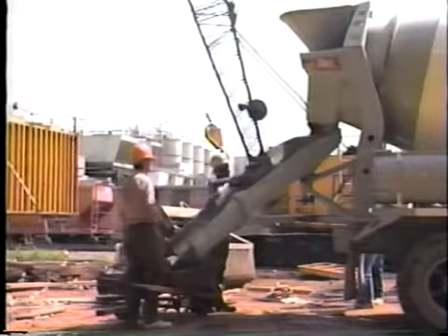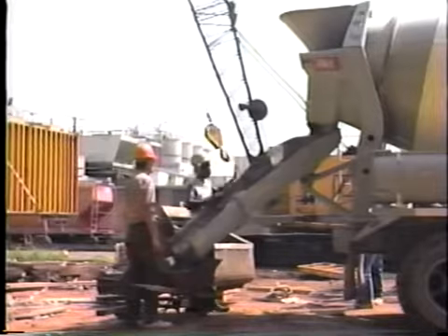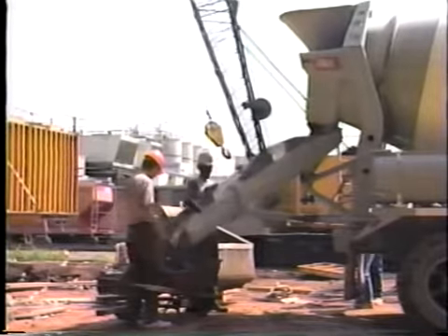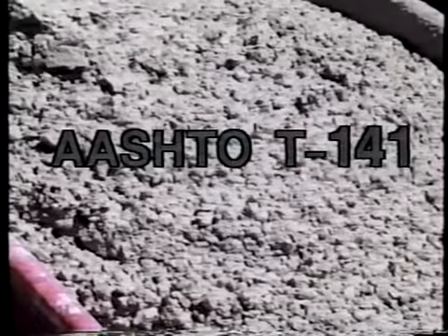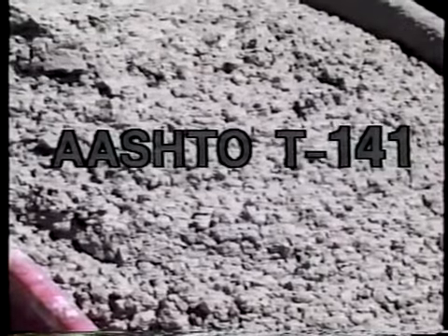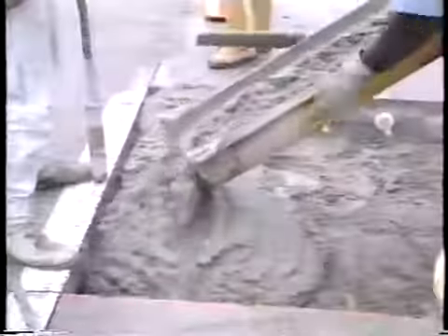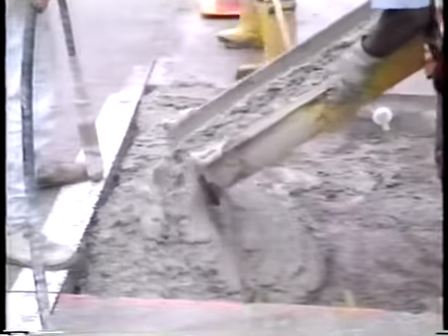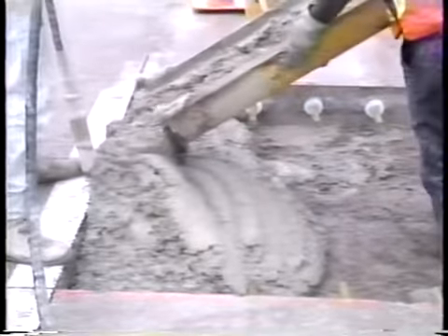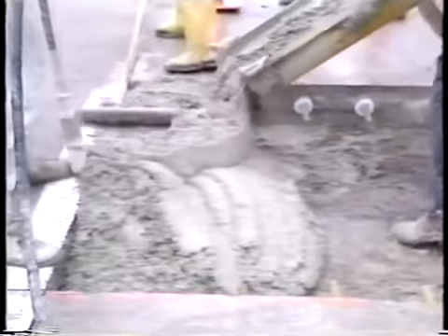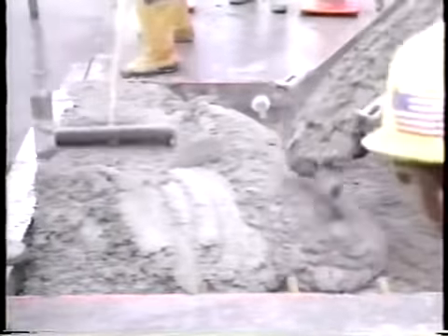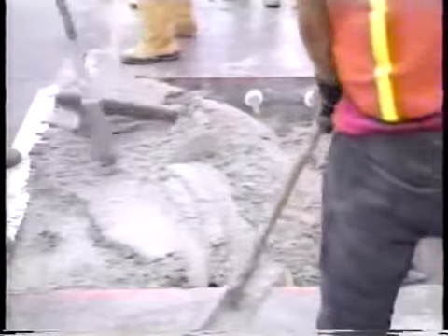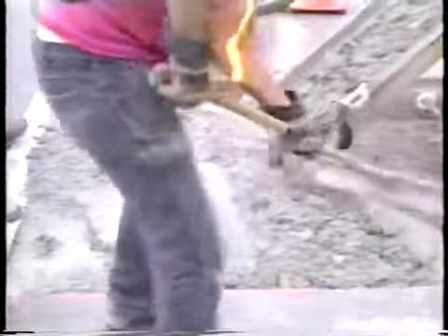The concrete to be tested has to be typical of the entire truckload. Sampling should be done according to AASHTO designation T141. The basic rule is this: don't take the sample from the beginning or end of the discharge. Take it from the first 1/3 of the discharge, but never from the first 2 cubic feet.